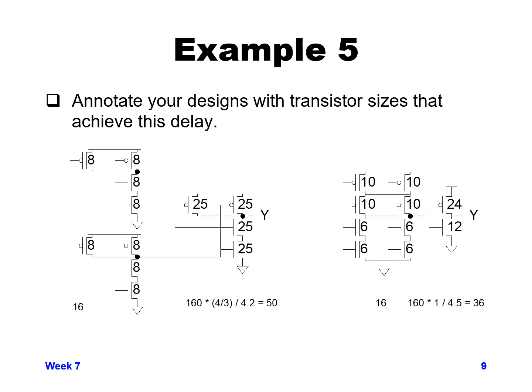So we take the C out that we need to drive of 160. We multiply that by the stage logical effort, small g. For an inverter, that's 1. And the value of f hat that we calculated on the previous slide for this particular combination was 4.5.